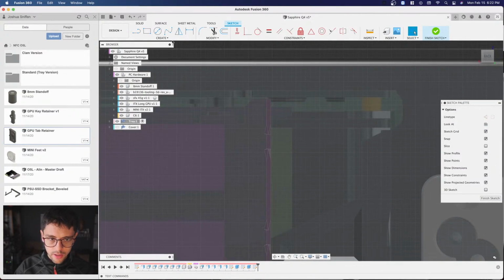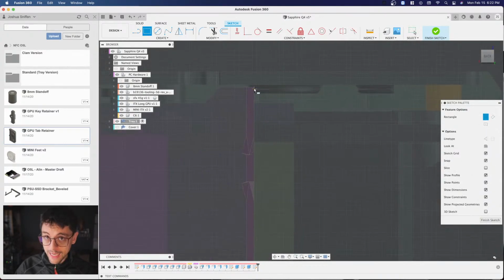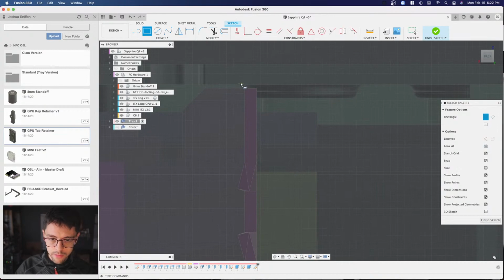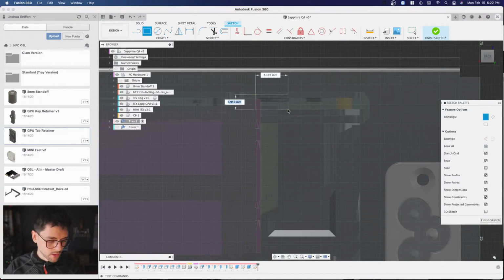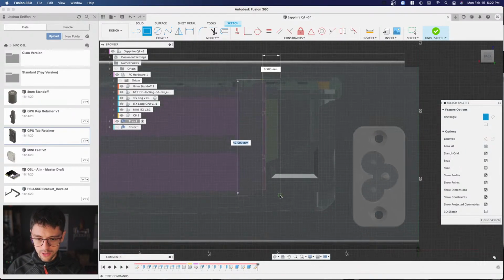I'm going to start from behind my flange because it needs to poke through. And we have to go up a teeny tiny little bit. It doesn't need to be a lot, but again, I like to have, this is a millimeter, I like to have a little buffer. What's the word I'm using? Tolerance built in for actually installing this.